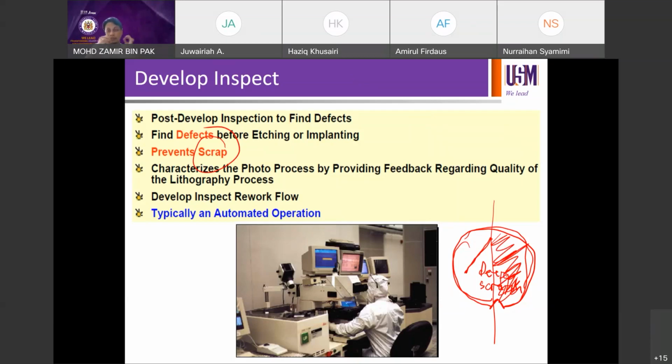Okay, maybe CD you can see it's on target on one side, but it's off out of spec on the other side. And then these are among the real things that you have to understand. You have to appreciate. You can only detect the problem while doing the measurement, but then the problem is not due to the process, but it's due to the equipment. Okay, so this is one of the cases that is possible. CD had a problem on one side, but it's always one-sided. One side okay, but the other 50% of the wafer is not okay, out of spec, out of control.